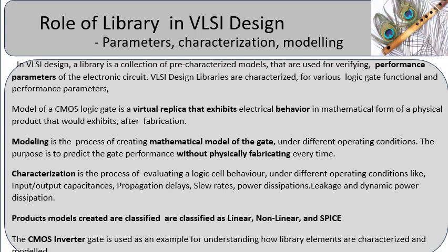In VLSI design, a library is a repository of pre-characterized models that define the electrical, physical, and functional behavior of gates used in the design and verification process. A model is a virtual characteristic representation of a logic gate. Modeling is the process of developing a mathematical abstraction of a gate, enabling analysis of its behavior under different operating conditions. This avoids the need for physical fabrication at an early stage.